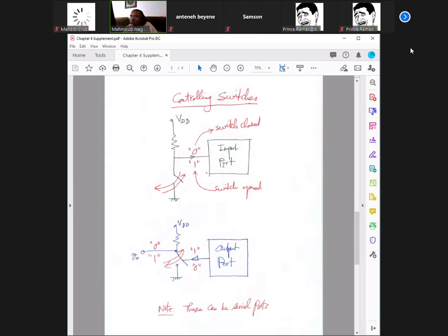And this data is going to go to the accumulator, of course. Reading the position of the switch means converting the mechanical position of the switch into data in the accumulator. That's the action of reading in the language of microprocessors. So if you read 0, that means that the switch is closed, short-circuited.